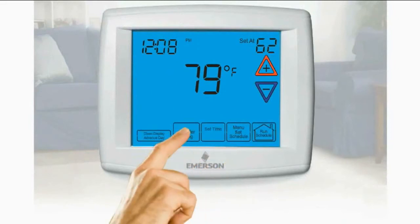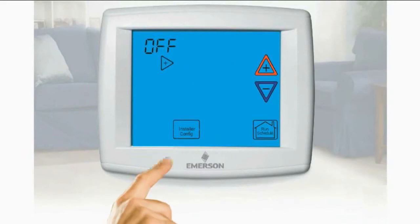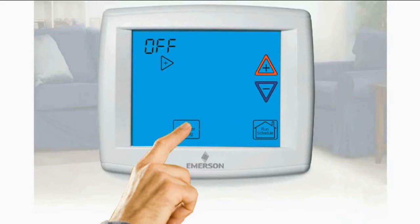Touch and hold the installer config key for approximately 3 seconds to enter the thermostat operations configuration menu. Touch and hold the install config key again for approximately 3 seconds to enter the advanced installer configuration menu.